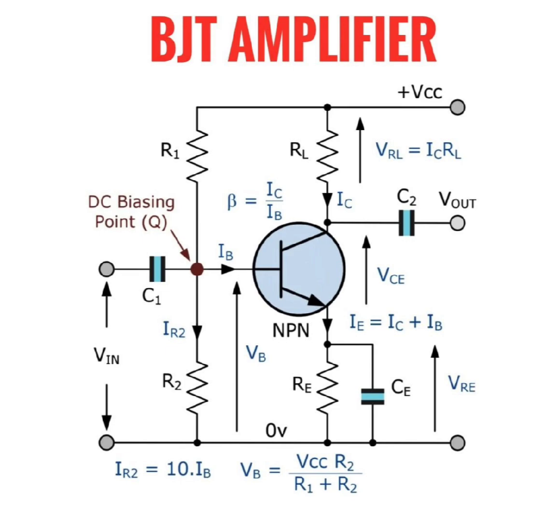Now reverse bias. It is when the PN junction is connected so that current cannot flow, or flows very little. In our transistor, the base-collector junction must be reverse biased. This is essential for operating in the active linear region.